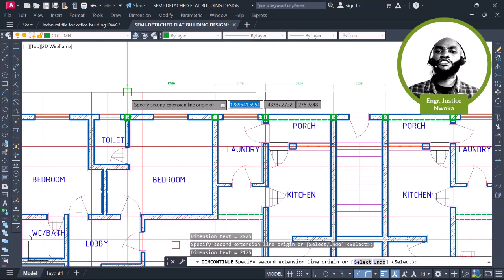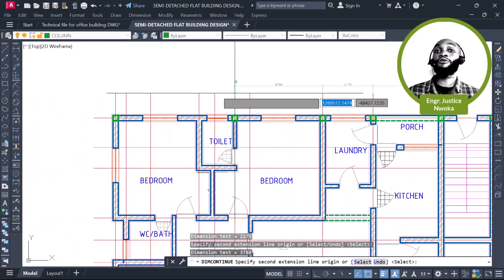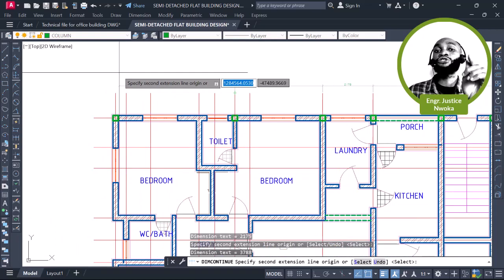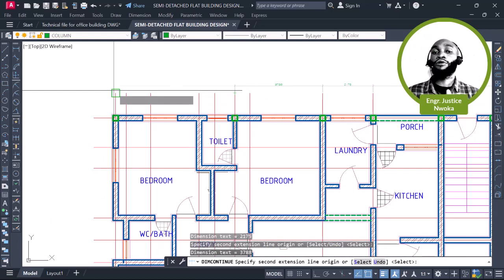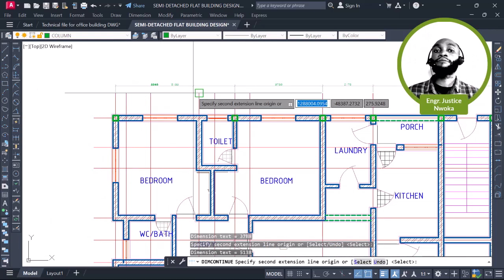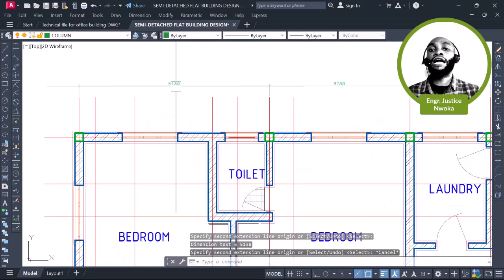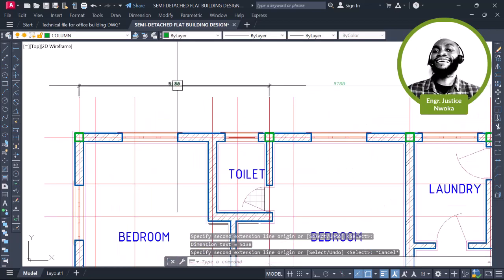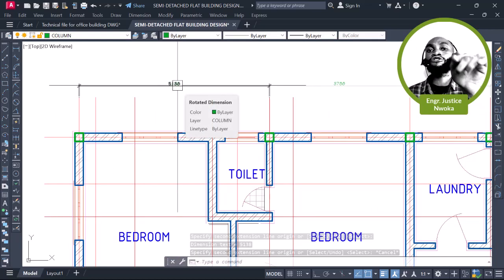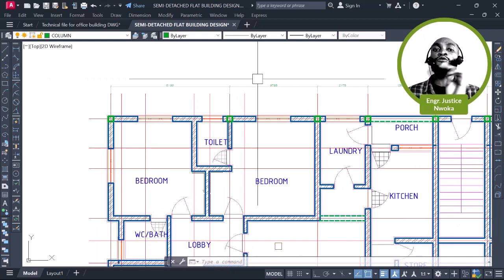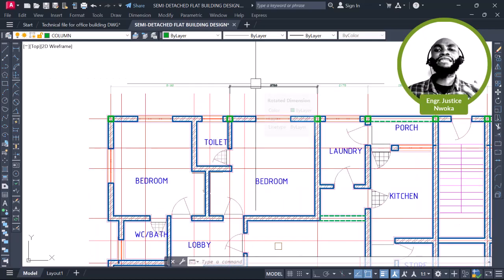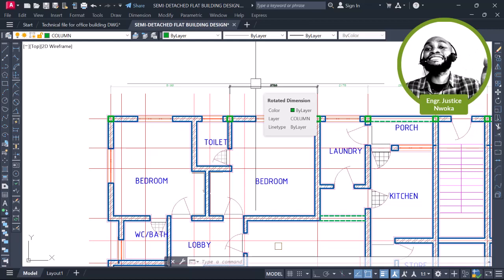Now most people see this as very stressful, but if you want to have issues in your design, don't do your GA. Most people think that performing their GA is a waste of time, but that is the most critical stage of your structural design, because that is when you are planning the stability of the structure by placing your columns and beams. So you must spend time doing your structural frame.